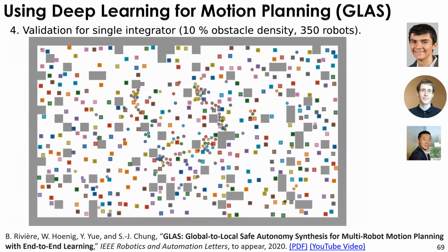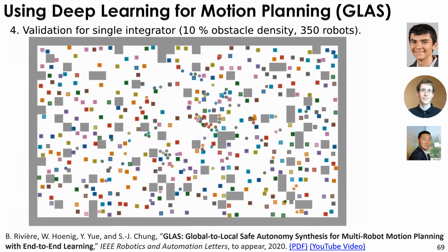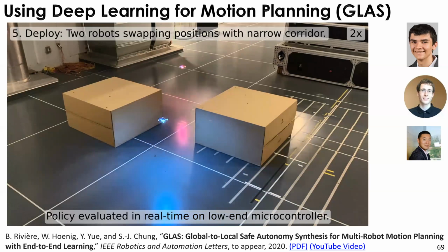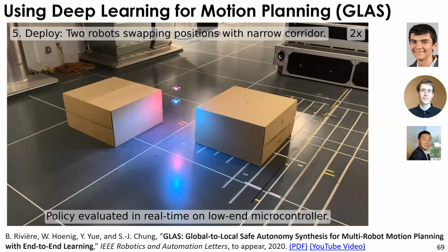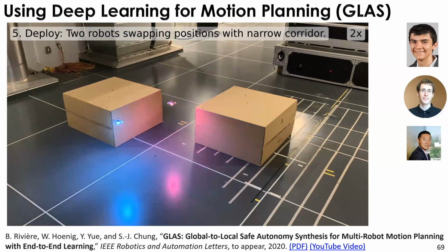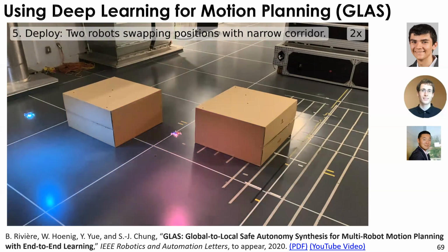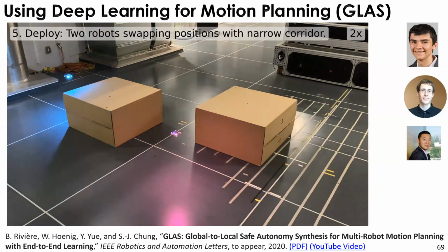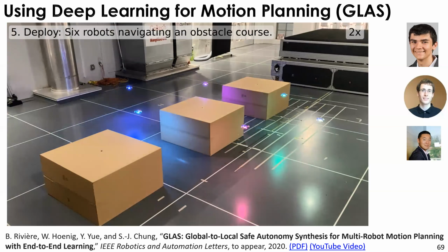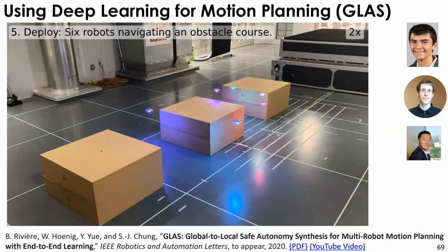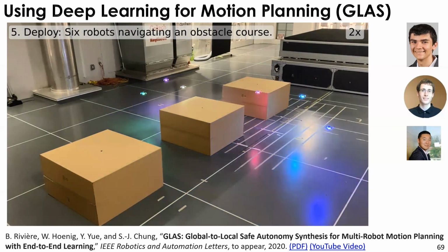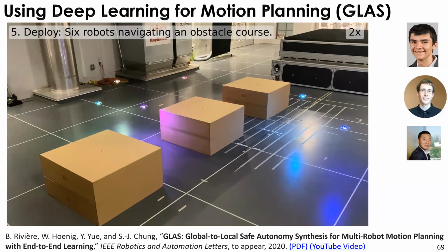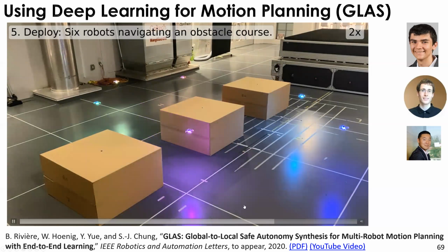And then you have a local safety filter to ensure that it's like a PD control with a certain barrier function or safety filter, so that they don't collide with each other, while still following some desired trajectory. It computes from the evaluation of a deep neural network. Again, the deep neural network is based on deep set. It mimics some desired optimal trajectory you pre-compute using imitation learning, using some expert demonstration. And the expert demonstration here again is a centralized optimal motion planning. And then we can demonstrate that for multi-agent systems.